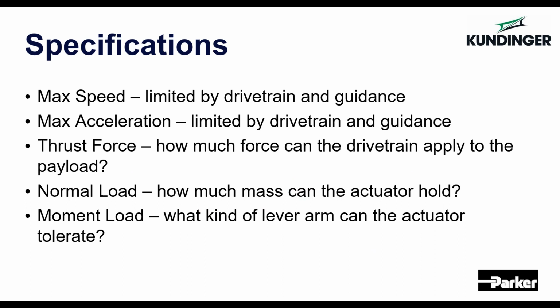Thrust forces, really how much force can the drivetrain apply to the payload? So how much force can I use to push things forward or backwards? Determined by acceleration, friction, and horizontal and vertical applications. You're obviously going to be coming up against gravity as well. But payload acceleration and friction typically end up determining what our thrust forces would need to be, or if we need to apply some sort of pressing force as well.